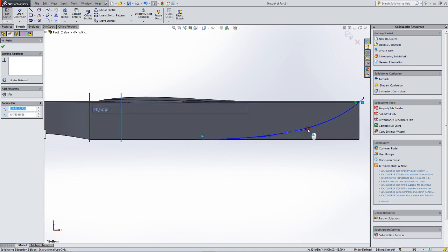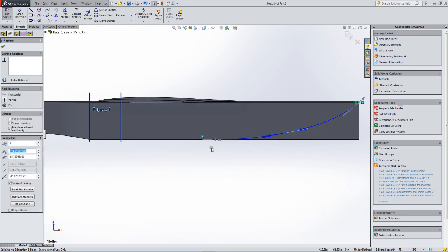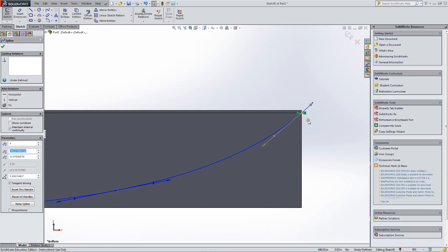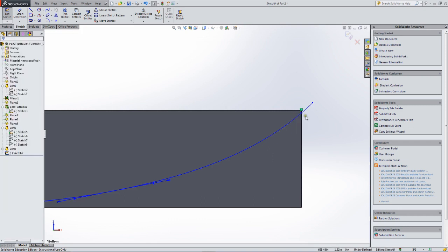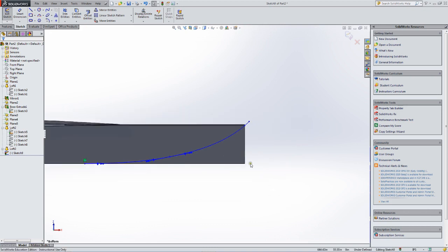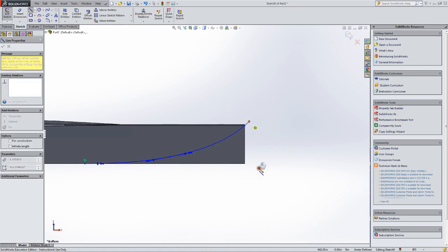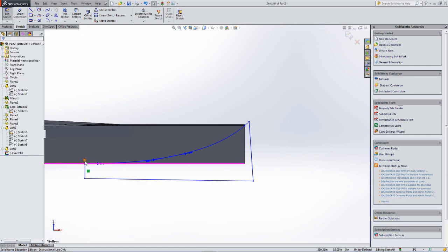And I can use this to make it tangent down there. I could also use that one to make it tangent down there. More gentle taper of this rear fuselage. Imagine the engine sticking out down here or something like that. Alright, so that's what I'm going to do. Let's check that. Again, I'm going to turn off these locks. Well, that's a pretty decent thing to do. But remember I have to make it a closed curve, so now I just make a box here and close it up.